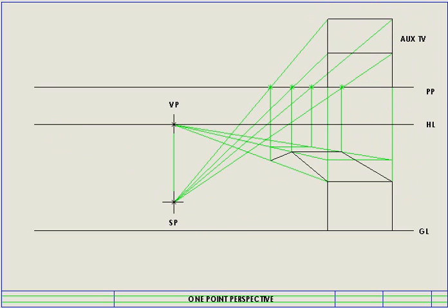Okay, now I'm going to go ahead and do the bottom portion of this house. I'm going to be connecting that point to the vanishing point, and I know that this point over here has an upper and a lower point because this is the top view of my house. Okay, so therefore when I follow it, it must also have a top point and further down a lower point.